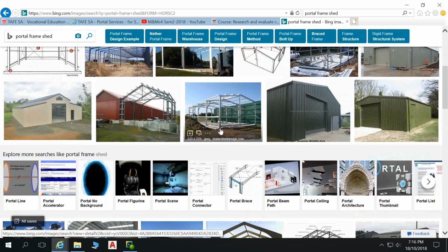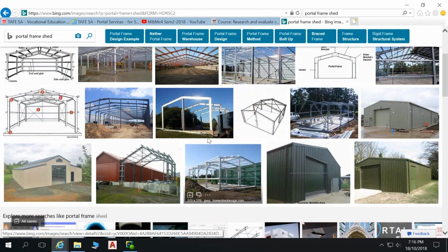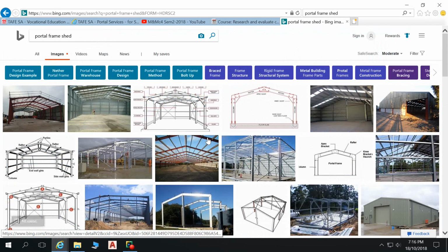Now those portal frames, they'll mount to a concrete structure beneath with that detail that we showed before with the plate fixing and the nuts underneath, the adjustable nuts. And then once it's all set in place, you use a non-shrink grout underneath those plates to keep them rigid, so they don't just rely on the bolt fixing, but they've got a grout bed as well underneath them. So this is what we mean by portal frame construction, but it's not simply limited to industrial buildings, etc. You can also build a whole house using portal frame constructions. Or even domestic sheds, etc.